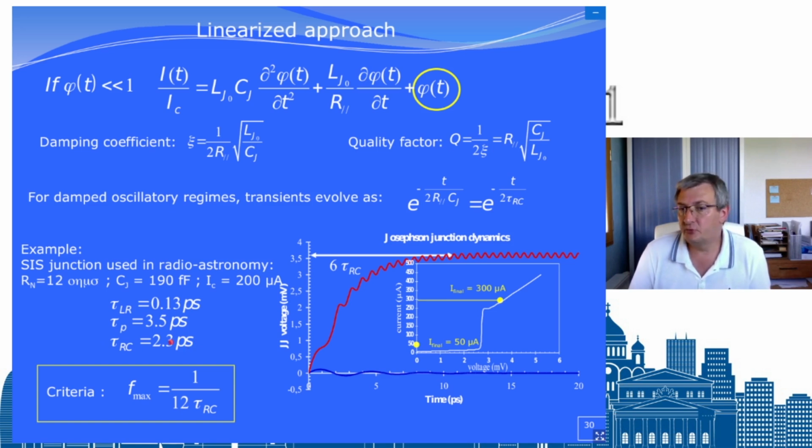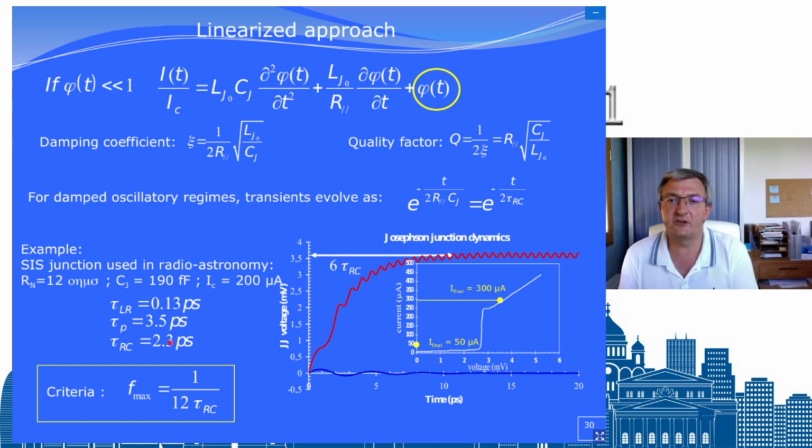So it's easy because you just shunt. That's why before I showed you a resistance in parallel with the junction. You shunt the junction with a small resistance. A normal resistance, you put a molybdenum or well, material that you are used to in microelectronics clean rooms. And then you can reduce the resistance.